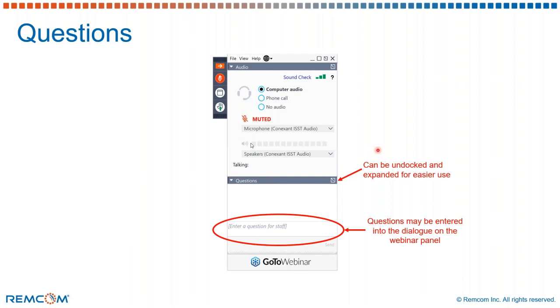And the next question is, what are some of the parts on which the singularity correction can be enabled on? So singularity correction should be enabled for critical metallic design components where you have strong and rapidly varying E and H fields. So the antenna radiators, for example, for a patch antenna, the radiator would be a component on which you would want singularity correction to be enabled, or any sort of transmission lines which are nearby, and also for resonators.